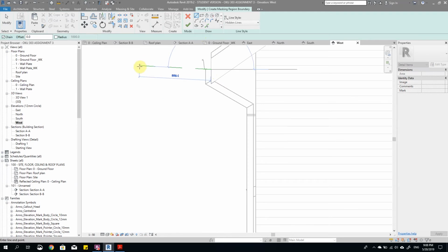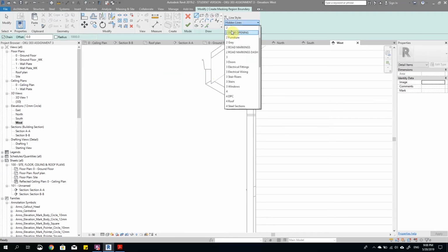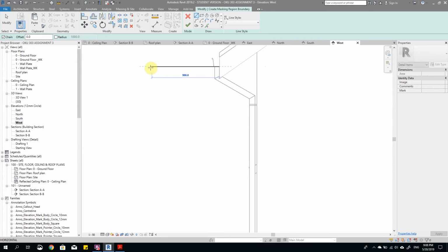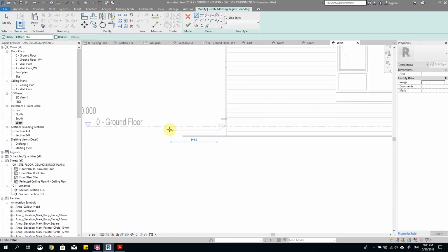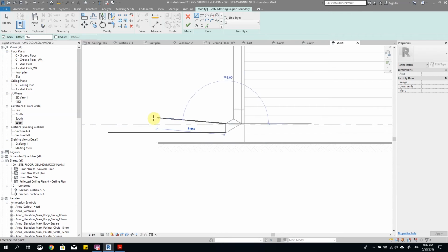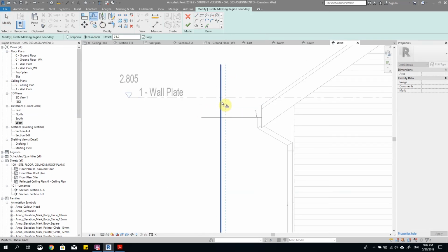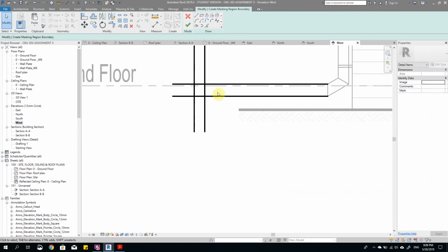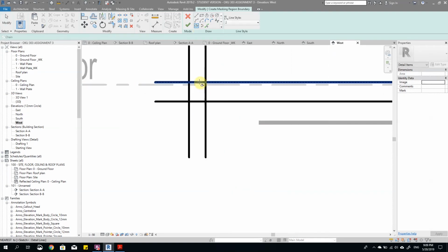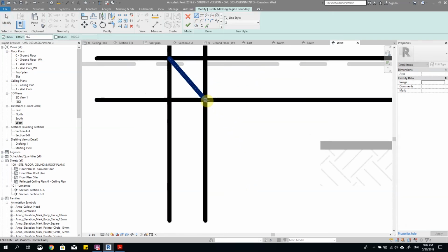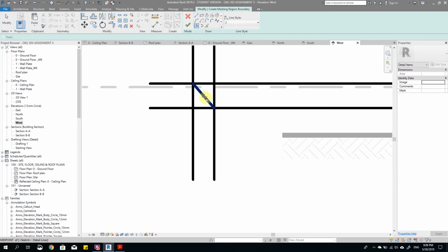I'm just going to pull some of these. So let's select layer 2. Grab this, this, and this. Okay, I'm going to grab this line here. Offset that by 75. Okay, so we know that this is our circle, so I'm going to use this tool. I use one detail line. Okay, use this ellipse tool, select the center, pick from there to there.